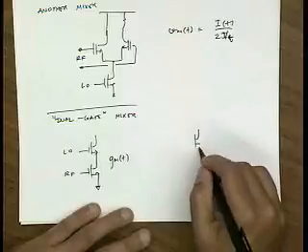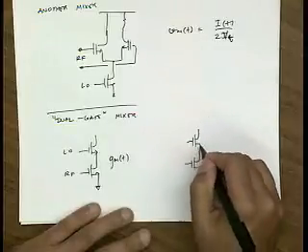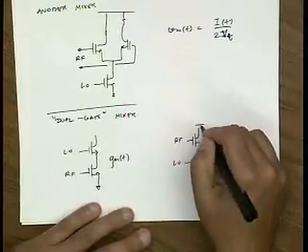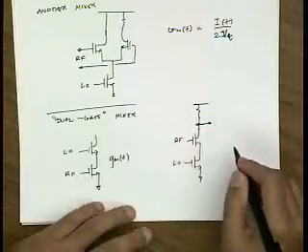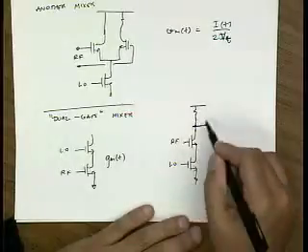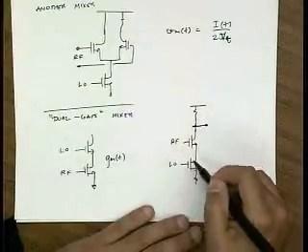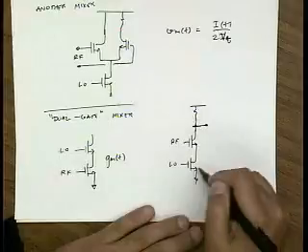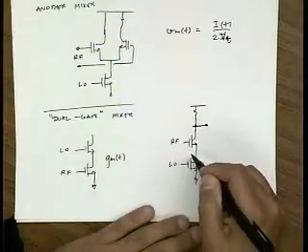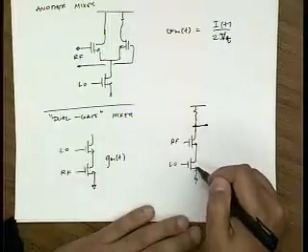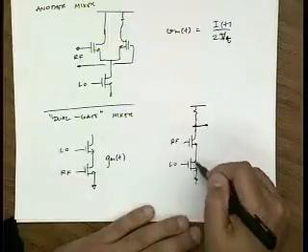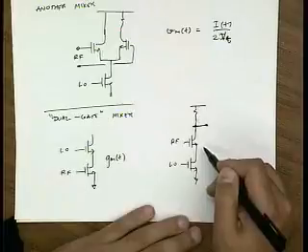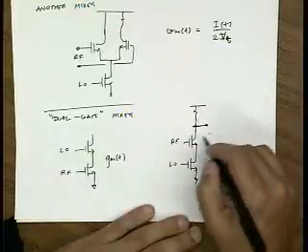On the other hand, if I switch things around, you can see that it's not a very good mixer. If I put in my RF here and my LO here, from the RF perspective, this is a very low gain amplifier because this is a heavy amount of degeneration. And by changing the amount of LO, I do change the degeneration somewhat, right? But then I have to do something very drastic. So for instance, if I make my LO very negative, this transistor goes into cutoff, and then you present a certain amount of degeneration. You still have bad gain. When you turn this thing on, it turns into a current source, and you have another amount of degeneration. And so you still have bad gain. So this always has low gain.